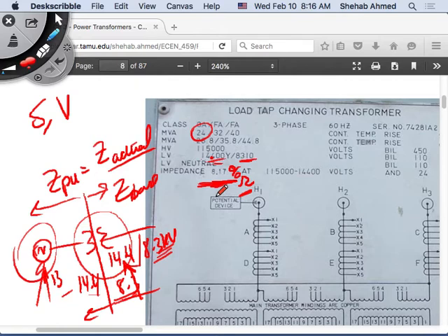So for every equipment you will have to look at its parameters. If they're given in per unit, it's using its own base or own ratings as base values. Okay, so it's using the machine's or the equipment's ratings as base values. I bring in equipment rated for different values now into the system, right? This is a 24 megavolt ampere transformer, right? Rated. This is its rated power. This is the S base that I've used for the transformer.